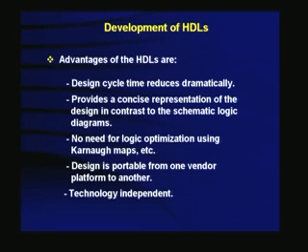As I said, the HDLs have many advantages. Design cycle time reduces. It provides a concise representation of the design in contrast to the schematic logic diagrams. No need for minimization, all that is taken care of. Design is portable, that means I can have a description, use one particular FPGA, and if I am not happy with that particular vendor, I can go to another vendor and use the same description.